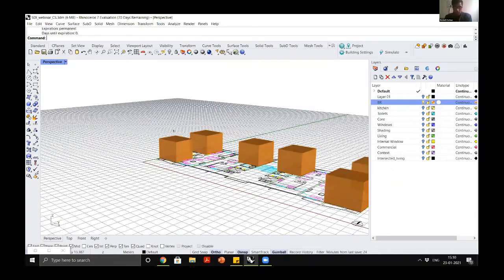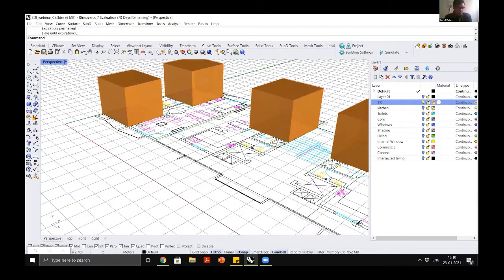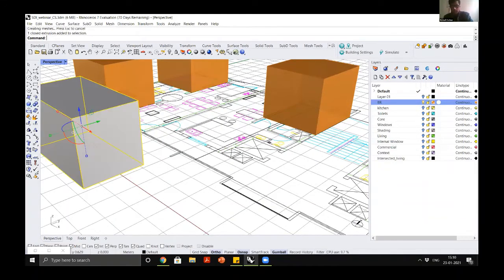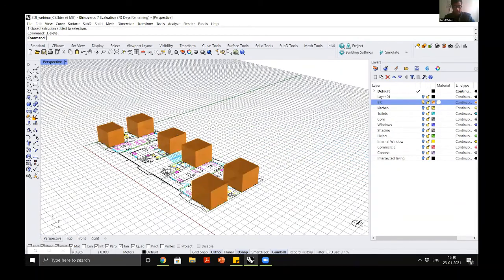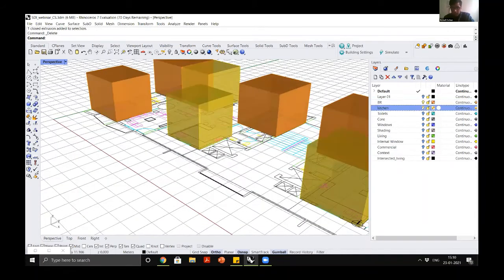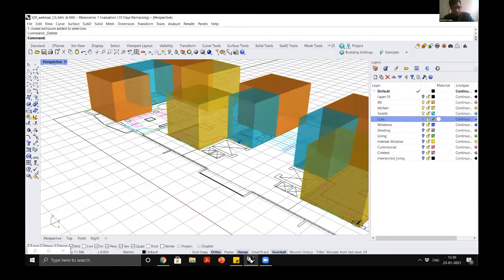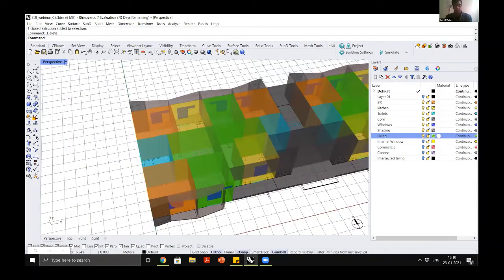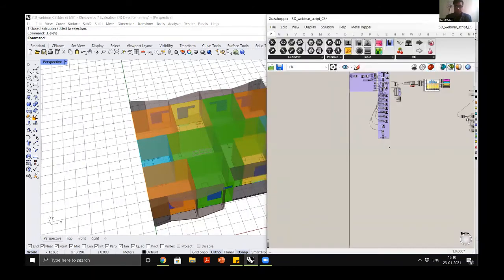So in this model, which I have created from the box in Rhino, we have created different zones, as you can see, and all the different zones have been developed in different layers. So I have a layer for my bedrooms, place. It is important that all your lines are very clean and clear and they do not intersect, because all of this will start creating problems when you enter into the simulation software.